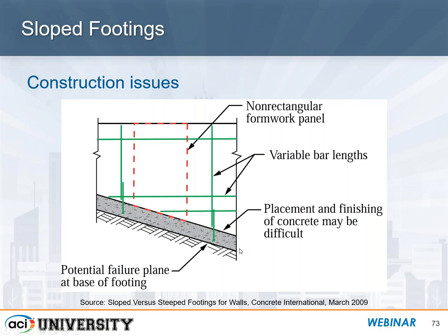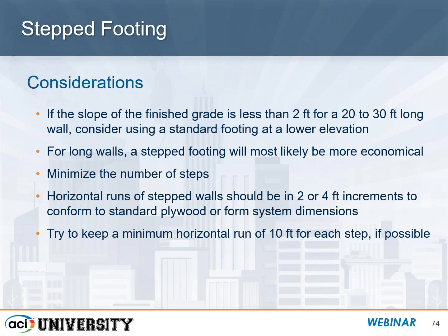If this slope is great enough, that concrete is going to be tough unless it's a very stiff mix. It's going to go sliding down the slope. So that's another very practical issue that you may run across. So in lieu of using a sloped footing, especially if it's a very steep slope, you should consider using a step footing. And what we have here are some general guidelines you should consider.